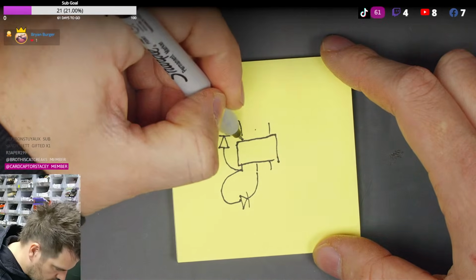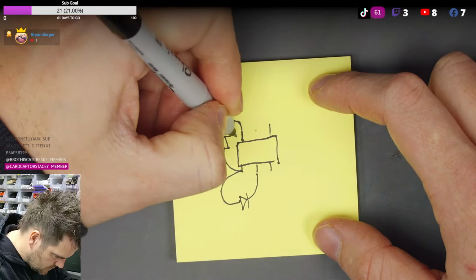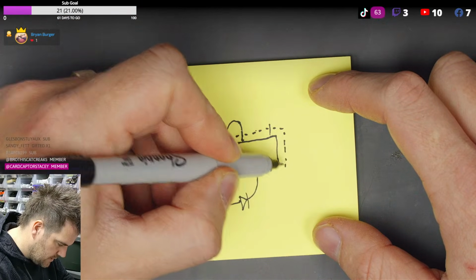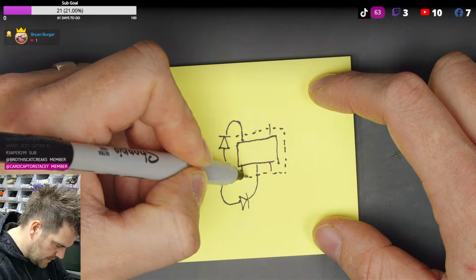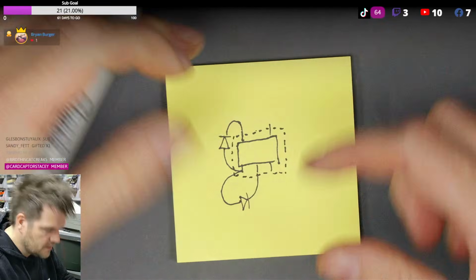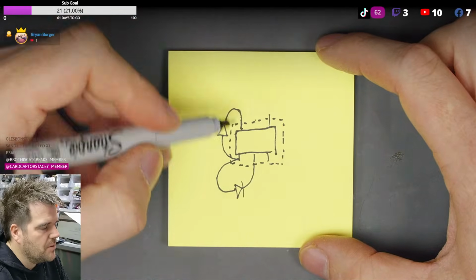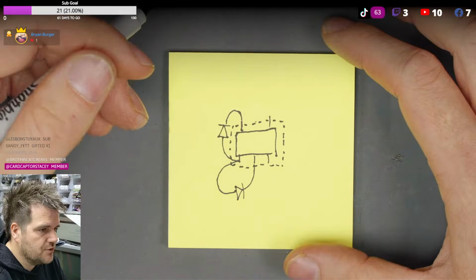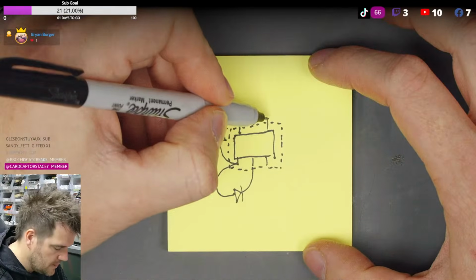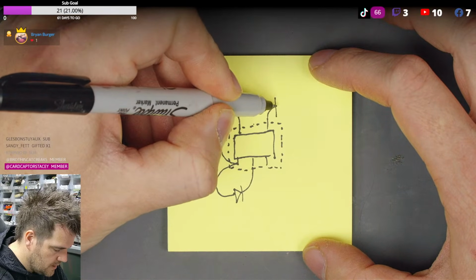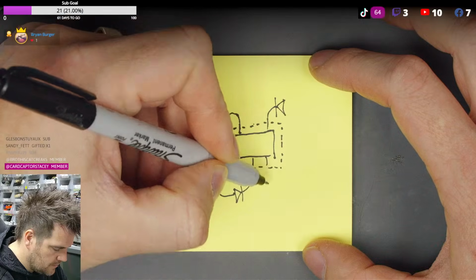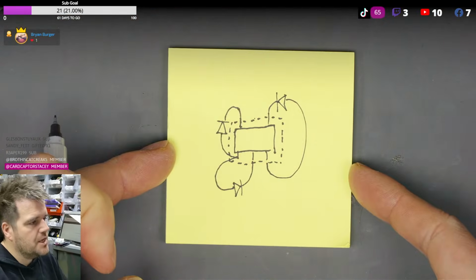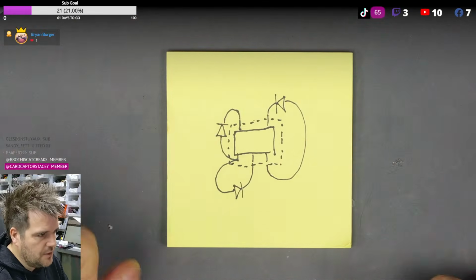And then obviously if I draw around where the pins are, so it's a little bit obvious where the pins are, I don't know if this will make it less obvious or more. We'll try and highlight where the pins are versus the lines. Yeah, maybe a bit more clear there. So you've got a diode here, and this might be a transistor in a package, but measurement wise we're getting a diode. This was also a cathode there with an anode to here. So that's what I'm seeing on the measurements, just pure diode readings.